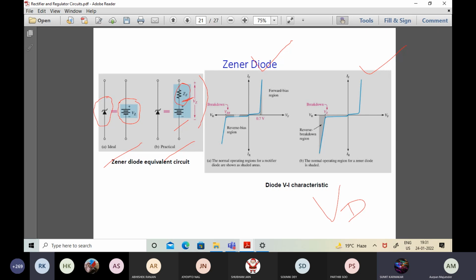However, when we talk about Zener diodes, the corresponding breakdown potential from where this sharp fall is occurring over here is at a much lower level normally. So that is the very quick difference that we can observe from these two graph representations. And the point is this: quantum mechanical tunneling of electrons, which leads to this increase of current, is far less detrimental compared to the case encountered in the context of avalanche multiplication.